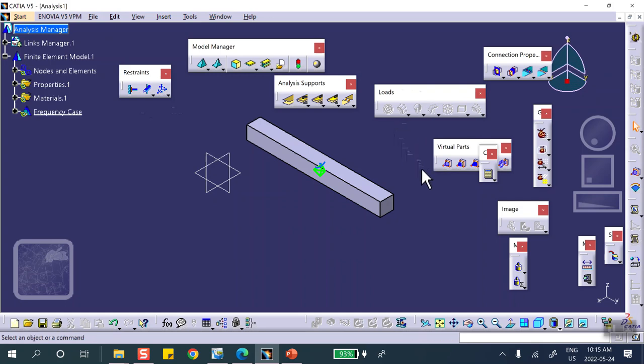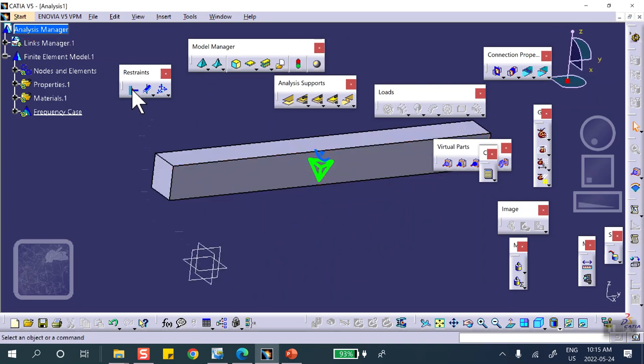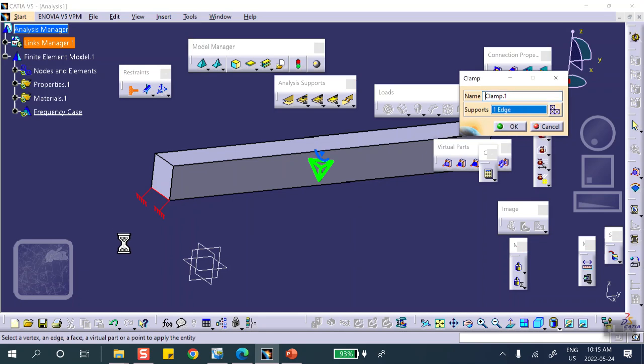Now, okay, so let's do a restraint. The first way, the more straightforward way, is to say, okay, this end, I'm going to pretend that is a pin. Pin means that it doesn't move in X, Y, or Z. So that edge is simply supported. It can still rotate, but it does not go anywhere. Don't do the face. If you do the face clamp, then this becomes a clamped edge. That angle stays 0 degrees.